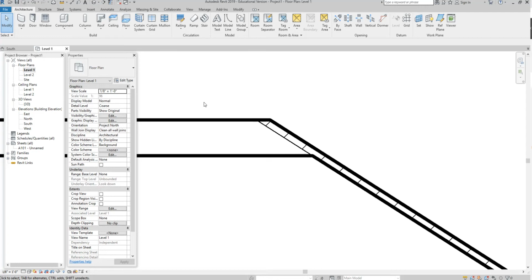There are going to be times where it's easier to have the line weights turned off when you're placing geometry. And it's going to be nice sometimes when they're on so you can see what's happening with them, right? One thing, if you've had AutoCAD before and you're looking at it thinking, well, how did those line weights get defined, right? Who told Revit this was a thick line and who told Revit that this was a thin line? Well, the beauty about Revit is that they're inherently defined in objects.